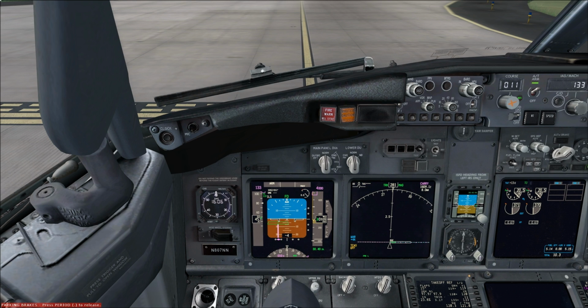It's also worth noting here that if windshear occurs during the takeoff roll prior to V1, there may not be sufficient runway remaining to stop if a rejected takeoff is initiated at V1. At VR, you rotate at a normal rate towards 15 degrees pitch attitude, keeping in mind that the tail strike limit for the 800 series of the 737 is about 11.5 degrees. So you rotate to that, and once the aircraft gets airborne, you aim for 15 degrees pitch. And then once you're airborne, you do the windshear escape maneuver.